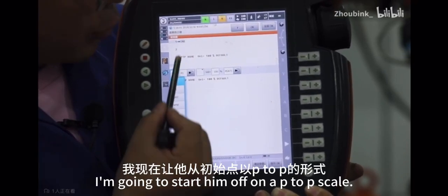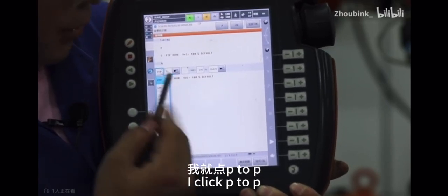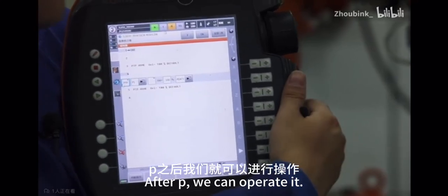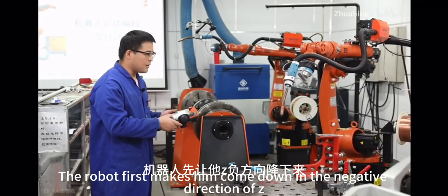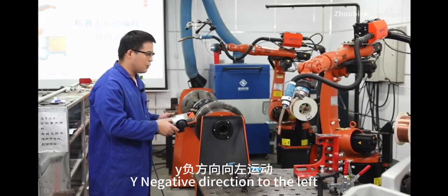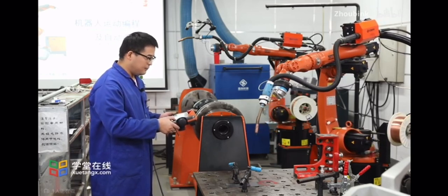Suppose I'm going to start with P2P to move to a point P. I click P2P. Click on the picture. We can operate it. First the robot comes down in the negative direction of Z. Y negative direction to the left. X moves forward.